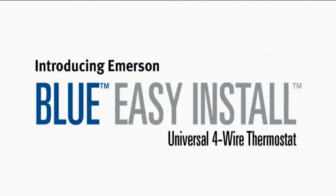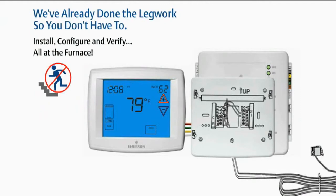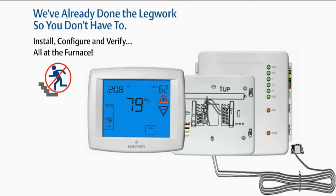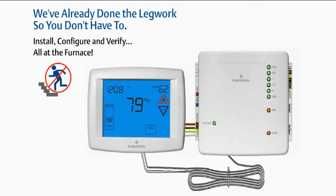Installer configuration menu for the easy install. The control can be configured at the equipment by utilizing the configuration plug-in tool, the F4 1400. The tool mounts to the back of the interface and plugs into the bottom of the control via the RJ11 connection. With control powered, the interface is used to configure the application and for operational checks.